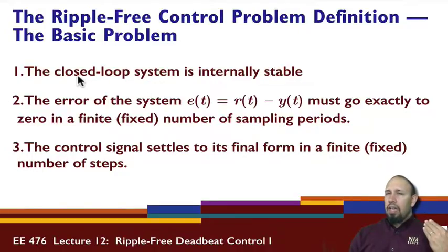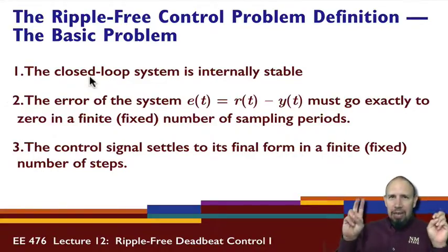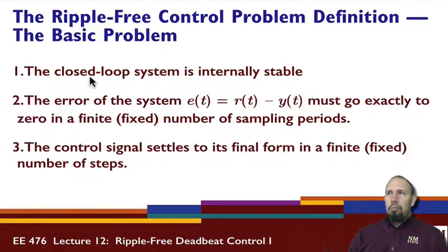And it's possible to design controllers for systems that are stable in the sense of the transfer function, but with pole zero cancellations for poles that are in the right half plane. That's generally not a good plan, in which case the system is not internally stable. The overall closed loop transfer function might look stable, but it's actually not internally stable.